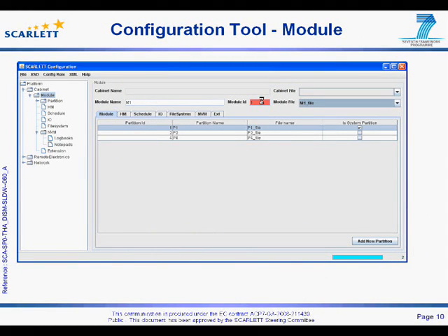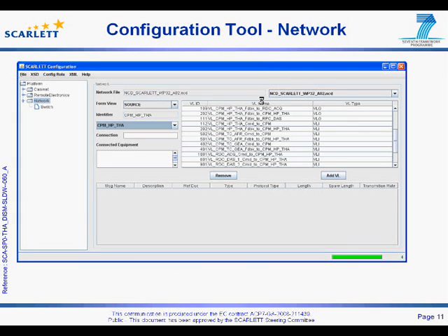The module interface allows the addition of partitions and the definition of health monitor tables, module schedule, file systems, and I/O interfaces. The network interface allows the definition of virtual links and messages that are processed over virtual links.